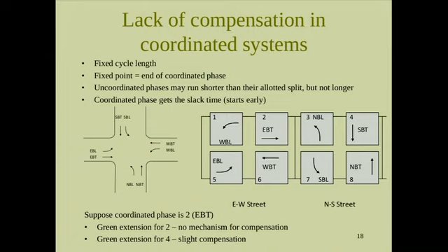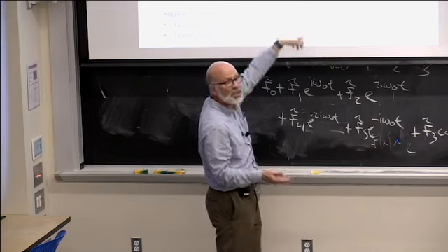So the east-west street has its time. There's an upper ring and a lower ring, and the rings that are in parallel, they can move together. So when the light starts green, eastbound left and westbound left, 1 and 5, they're green together. What comes next, 2 or 6?